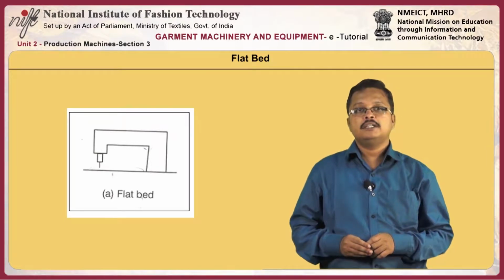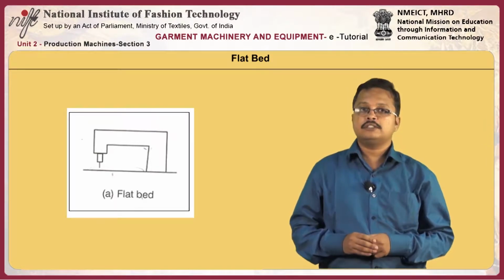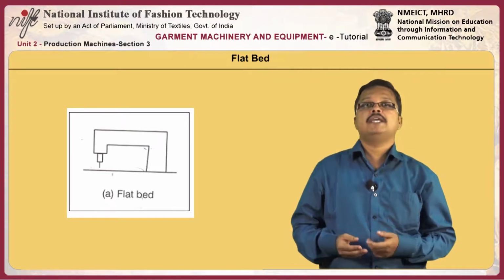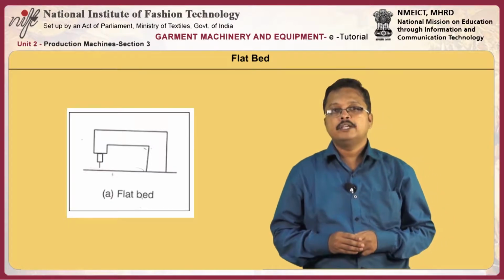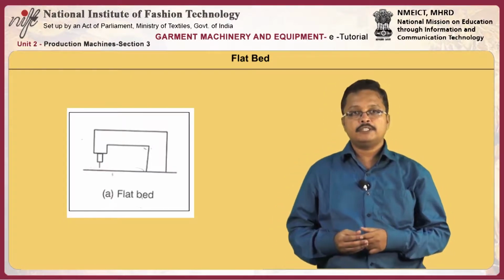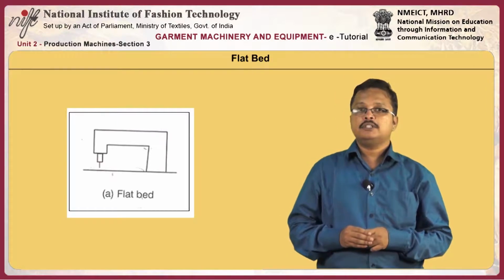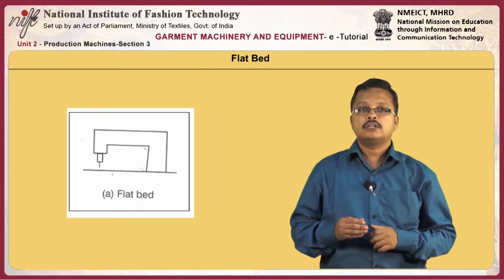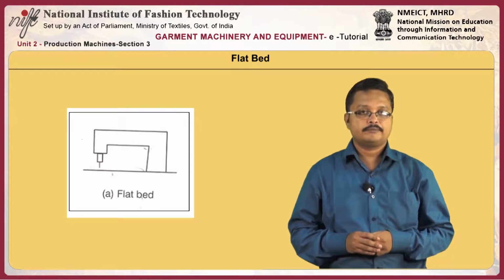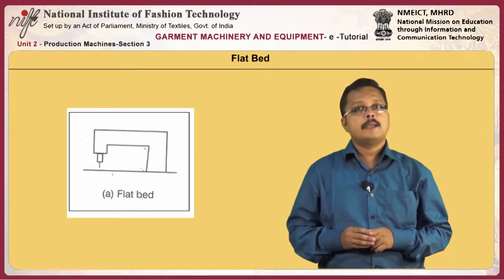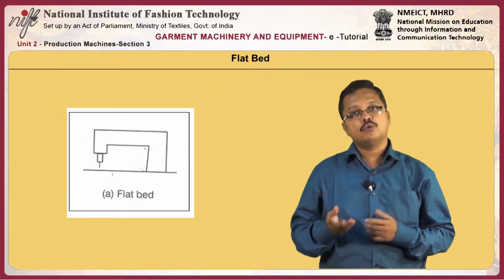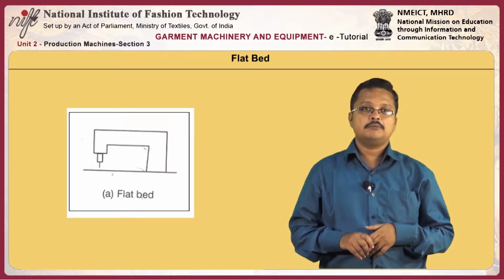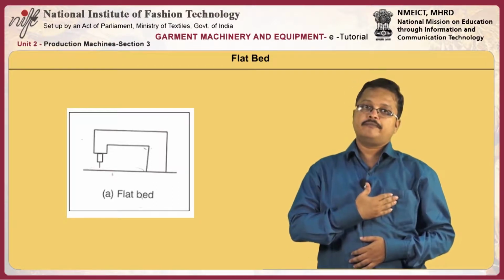The flat bed is used in most sewing techniques, where a large and open garment part can easily be handled past the needle. It provides a suitable surface for much flat sewing and also facilitates the use of markers to control the position of the garment parts. The machine allows manipulation of fabric on both sides of the needle for top stitching and lap seaming. For example, a patch pocket on a shirt front.